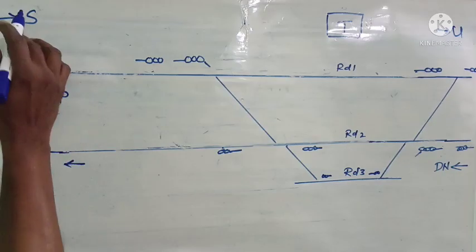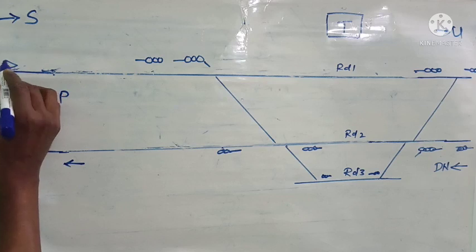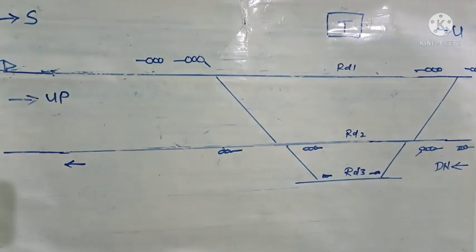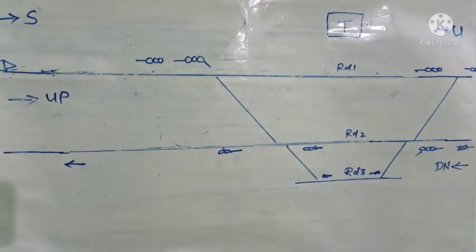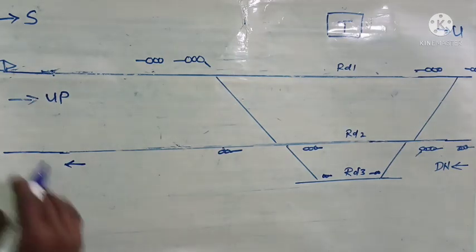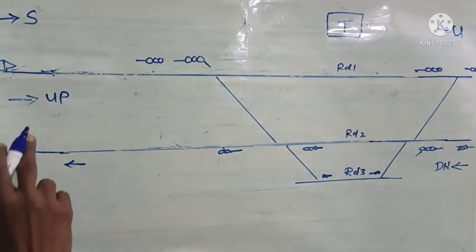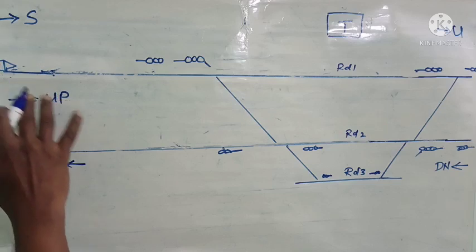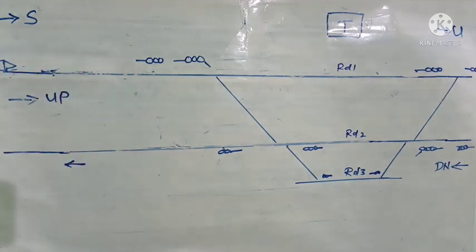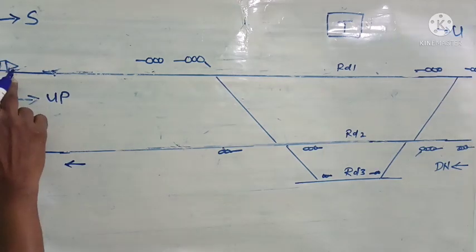The train which has left station S is fast approaching the station, and on reaching here at this place, the loco pilot experienced a heavy explosion under the engine. So he immediately slowed down. However, there were 2 more explosions. So total 3 explosions below the engine. Then the loco pilot understood that it was the detonators which exploded under the train. That means staff has placed detonators on the track and the engine exploded the detonators. Now he immediately slowed down his train.